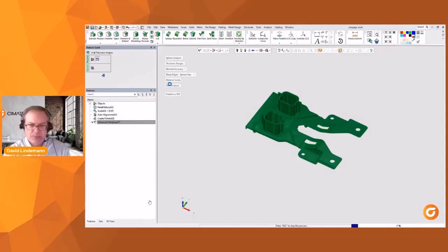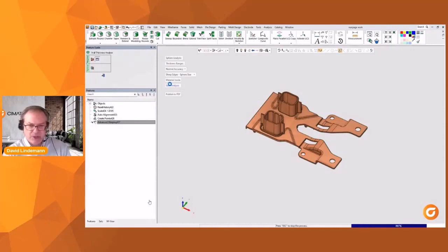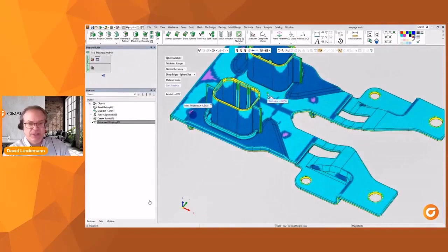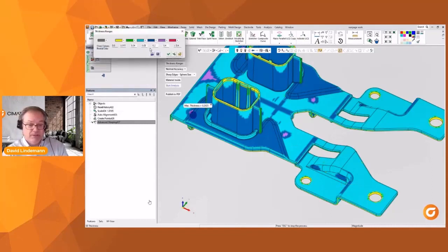So what this tool will do is wherever I pick on the part, it imagines a ball that would fit inside all those surfaces. So it's going to tangentially touch every nearby surface within that range. So see the cursor as I move it along the part? Those wall thicknesses are pretty consistent. Then other areas that were thicker, areas that I knew were thicker ahead of time actually, are still that same thickness as well. There on the left, you kind of can see, underneath the values here, this pull down I got, you can kind of see the max thickness.